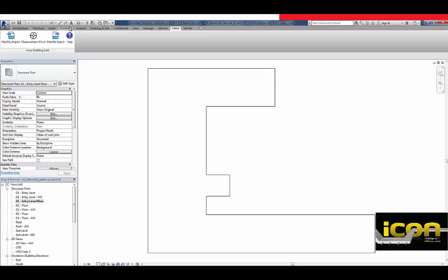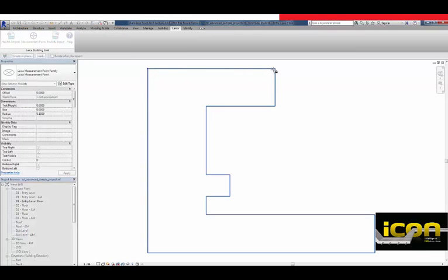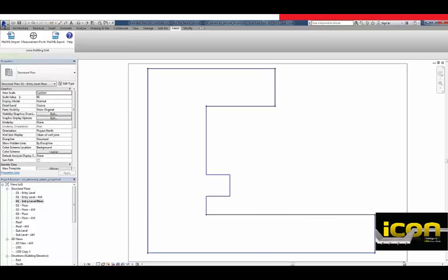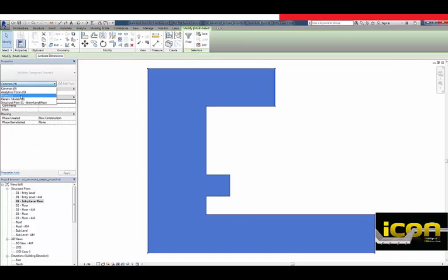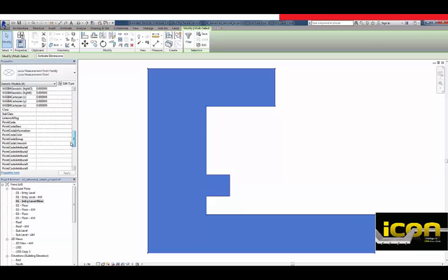Next, I will create the control data out of the building model, which will later be used in the field to set up my total station. I select the corners one by one using the Measure Point tool of the BIMLink plugin. Because you never know what obstructions will be on site, I will select more control points than I actually need for my setup. I give them the code name CTRL to be able to later filter for these points in the field.